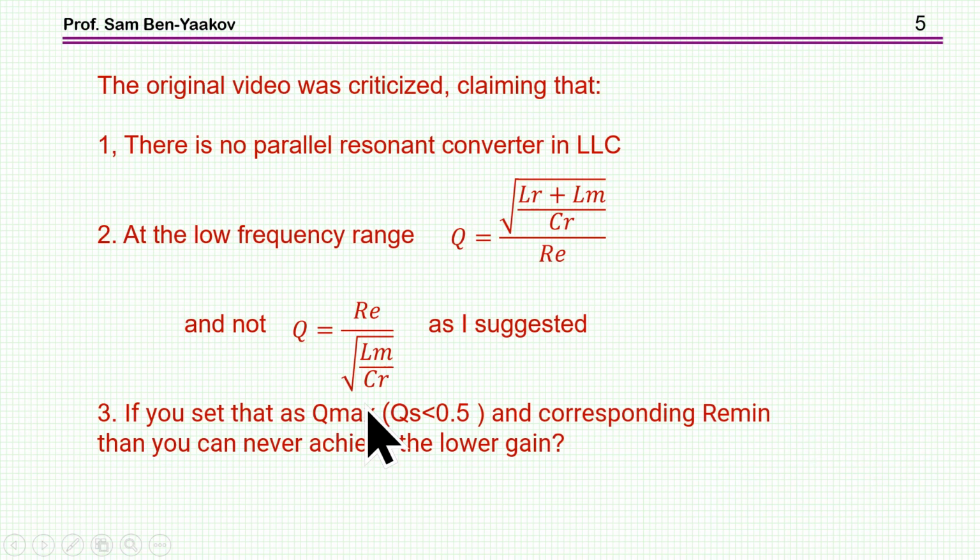Following the posting of this earlier video, I got some reviews and actually criticism, and I'm pointing out three major issues that were brought up. One is that there is no parallel resonant converter in LLC. No matter at what frequency range, this is not a parallel resonant converter.